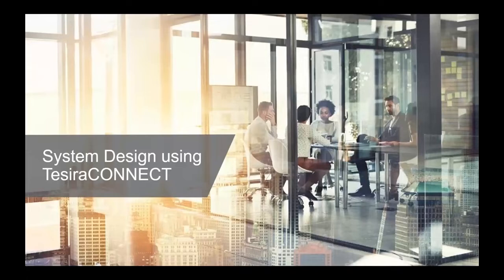Okay, so hopefully all of you are following along so far. We will put into practice whatever we learned in the slides thus far from Ahmed. I will talk about system design using TesiraCONNECT. I will focus on the TC5D, the media bridge aspect. The TC5 by itself is pretty much like a PoE switch that you can plug devices into and it all works. There's no special configuration needed besides the network settings and IGMP snooping.